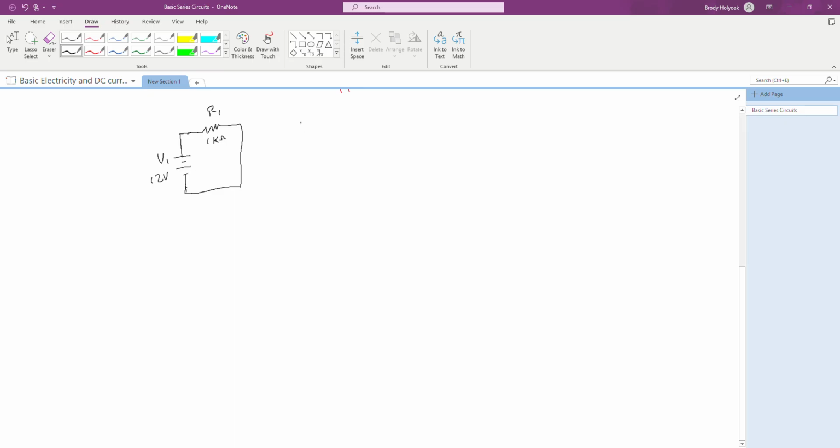So now when I do these same calculations, my current total is going to be the current going through R1, because it's a series circuit, there's only one current path, and my current path comes up from the positive of V1, around through R1, down this line, back across, and back up until we get to the negative of our supply. So again, calculation-wise, we are going to have the voltage of R1 divided by R1's value. That's also the same as my voltage total divided by my resistance total. And my resistance total is only R1. I don't have any other options.